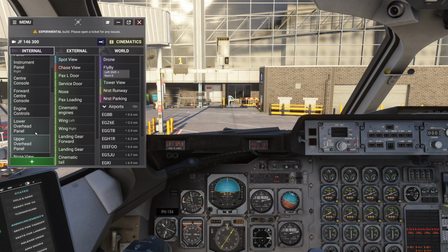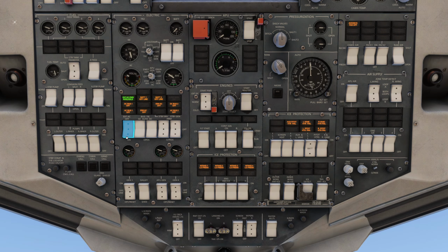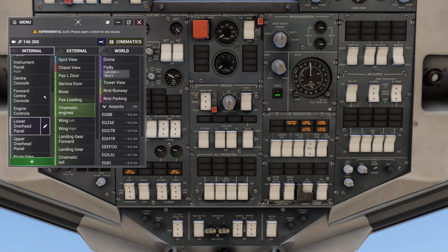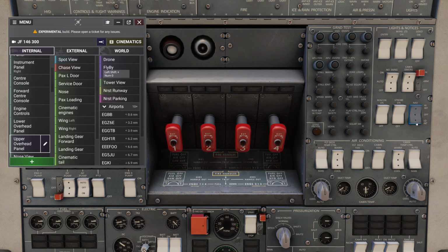Okay, I'm going to the overhead panel and set the external power to on. External power is on, so we can continue with the checklist, please. Perfect. That's great. Now that the external power is on and the battery voltage should be stable, let's move on to the next step. The next item is to turn on the navigation lights, and then we'll keep going from there. Let me know when you're ready. Okay, keep it short. Navigation lights on. Got it. Navigation lights on.